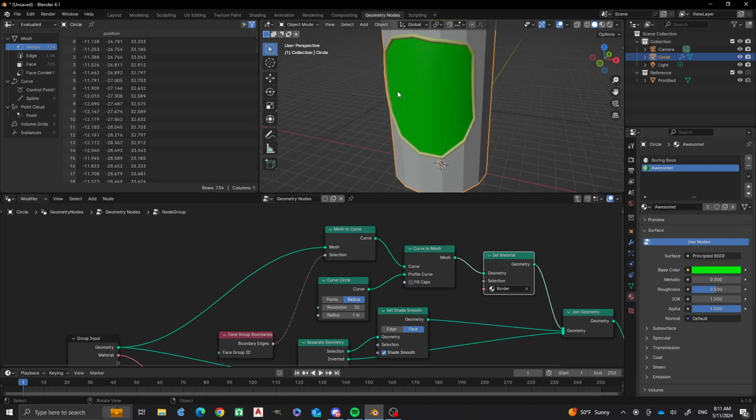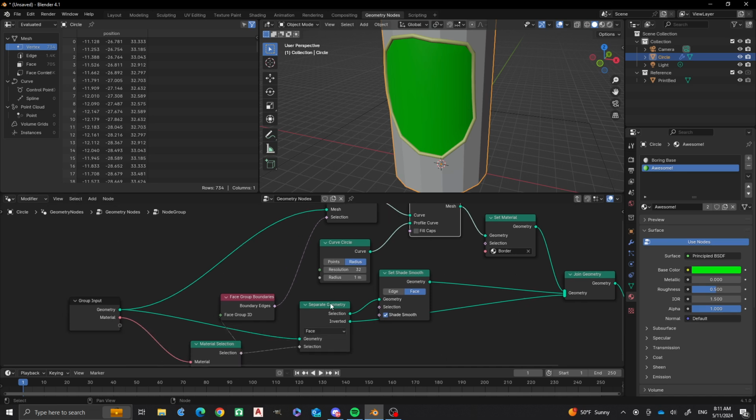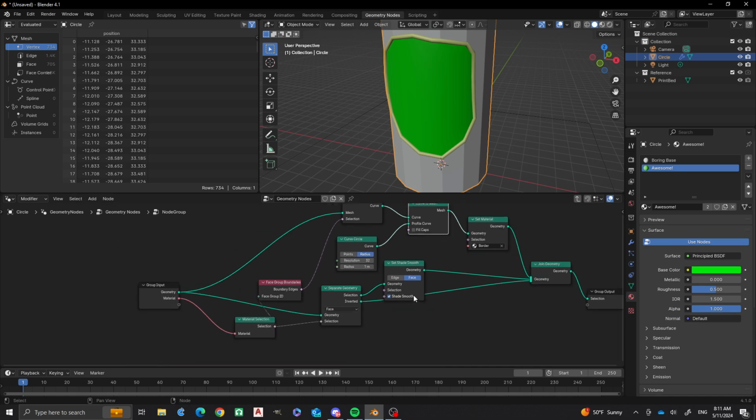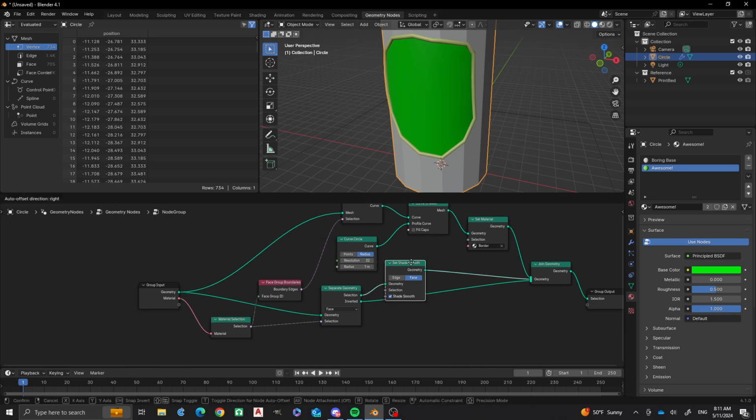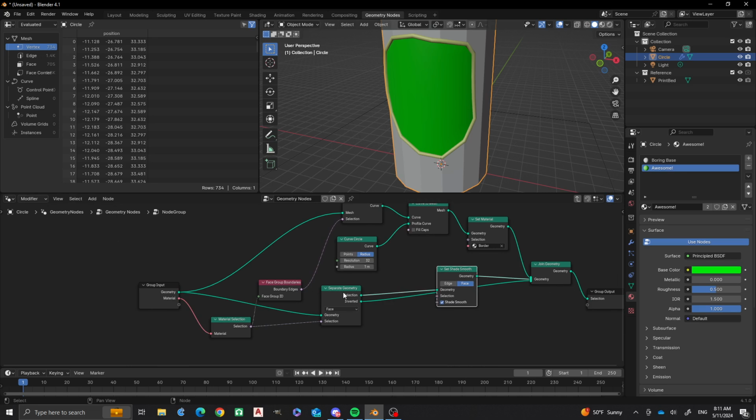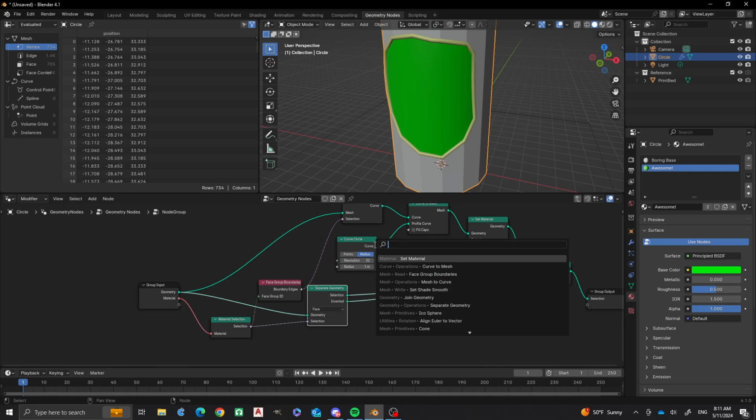Now, within the selection, all we have is just this blank area that's smooth, right? Well, now we just want to have something cool that we can do something with. So, let's generate some points on here. So now what I'm going to do is go onto this geometry and do points on faces.